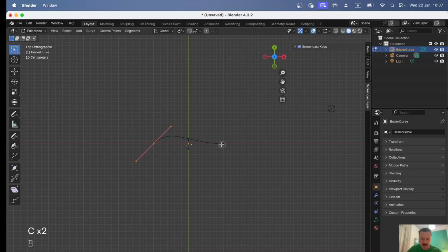And to do that, I will just select with circle, like so, or by pressing C, and then I get a more dynamic circle which I can play around with my middle mouse button. And by pressing the left mouse button and brushing against the curve, I can select it. And if I press double A, I can deselect.